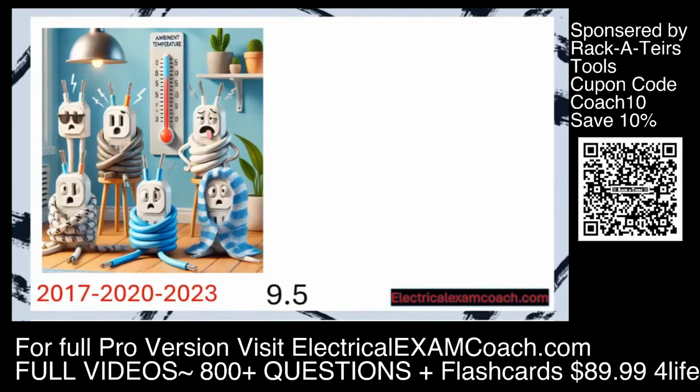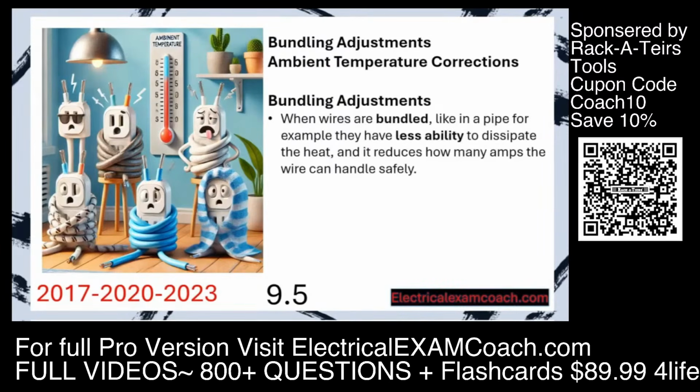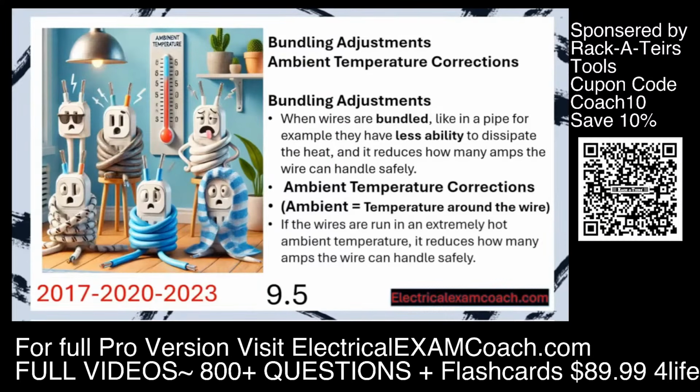And in this lesson, we're going to be learning about bundling adjustments and ambient temperature corrections. These are a subset of ampacity. And remember, ampacity is just how many amps the wire can handle safely under its conditions of use without exceeding its temperature rating. Bundling adjustments work like this. When wires are bundled, like in a pipe for example, they have less ability to dissipate the heat, and it reduces how many amps the wire can handle safely. Ambient temperature corrections are like this. If wires are run in an extremely hot ambient temperature, it reduces how many amps the wire can handle safely. We're going to learn about these one at a time.